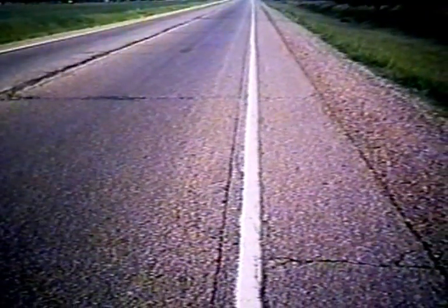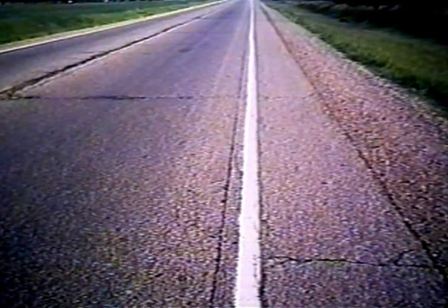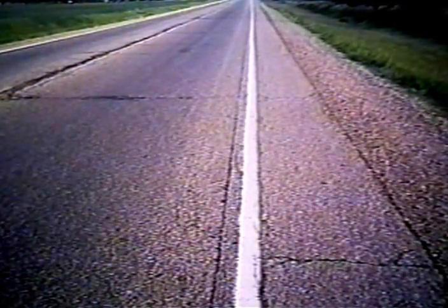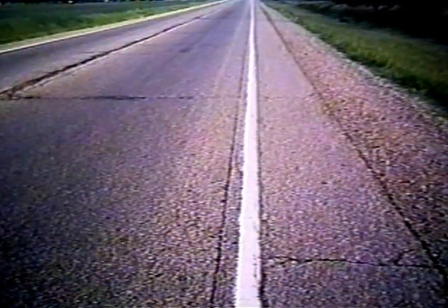Now let's talk about longitudinal cracks. When we build asphalt pavements, there are usually longitudinal joints caused by the paver. We're putting one layer of asphalt up against another, creating a cold joint, and this joint many times will open up with time. Here's a longitudinal joint that is in pretty good shape. Here's another example of a joint between the traffic lane and the paved shoulder that was paved separately. That joint now is beginning to open up a little bit.